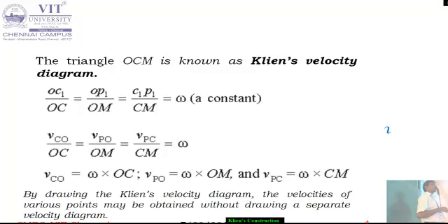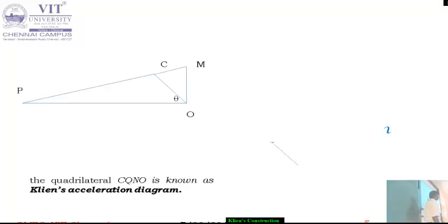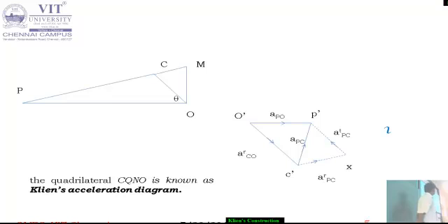Okay, clear? Because this is very important. Based on this, you have to draw the graphical method, by which you can calculate the unknown values there. So now take CM as radius, draw one circle. Take the connecting rod length as diameter, half of the value as radius, draw one more circle. So both circles intersect at one point.